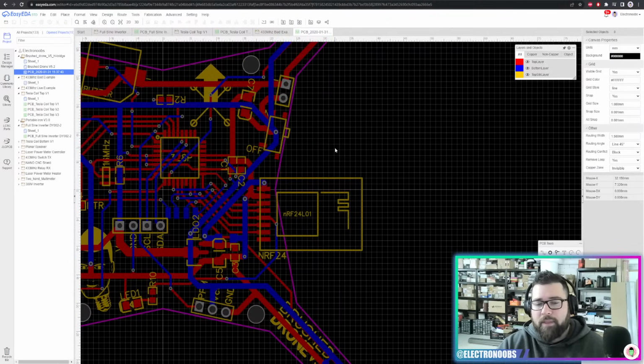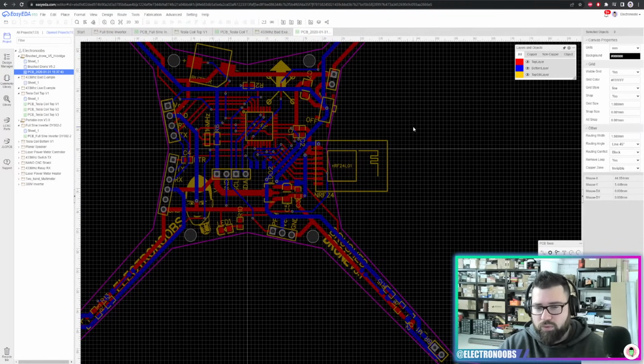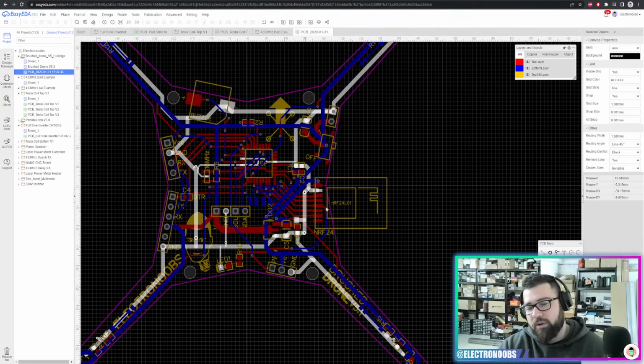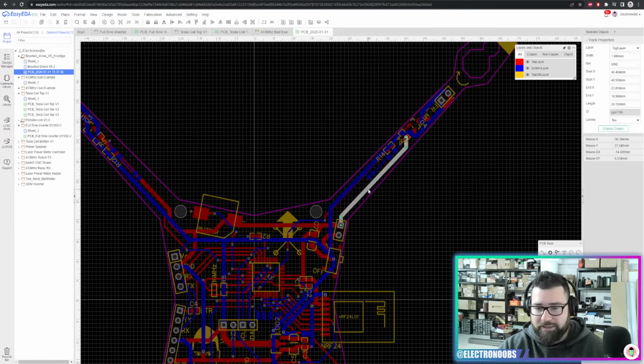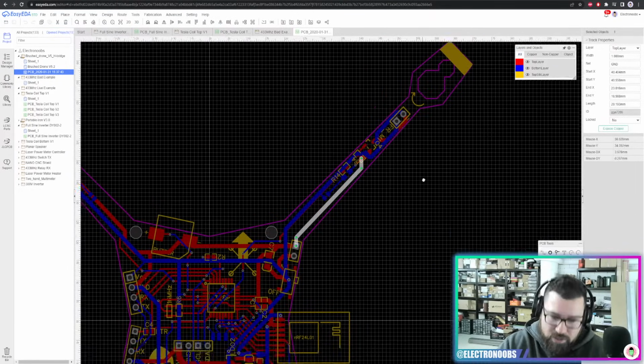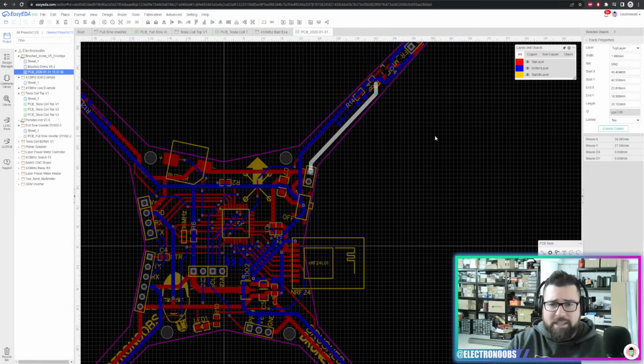So I've made a full video about how to take care of the noise, where to place the component when you're using radio. First of all, if you place it on top of your board, make sure that the power tracks, for example, this is a power track going to a motor and it is using a PWM signal. So basically that will turn on and off at a very high speed, and that will create a lot of current spikes. So a lot of magnetic interference and a lot of noise. So if you place your antenna above one of these tracks, you'll have a lot of noise and you won't get any signal.